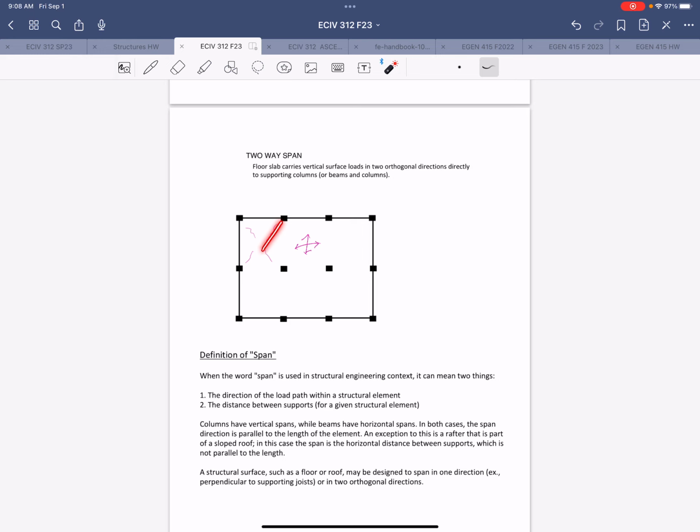And this is also then how we would divide up tributary areas. So kind of following those lines. All right, or I should say that would be the more accurate tributary area, the actual one. But in our practice, we would simplify it to lines that are drawn halfway to the next supporting column for those columns. So we'll look at that a little bit more later too.